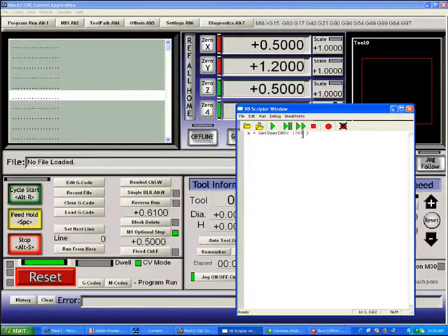and we tell X to take the value of getUser DRO 1200, and we tell Y to take the value of getUser DRO 1201, and Z to be equal to getUser DRO 1202, at the end of this Visual Basic run, the X, Y, and Z will be equal to the values which are in those DROs, and those DROs are persistent. Whatever you type into them, the program will remember from run to run.